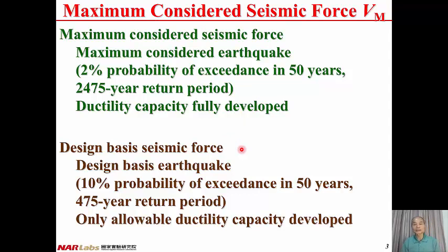And compared to maximum considered seismic force, design-based seismic force is the seismic force corresponding to the design-based earthquake, and only allowable ductility capacity can be developed. Design-based earthquake is an earthquake level with 10% probability of exceedance in 50 years, or a 475-year return period.